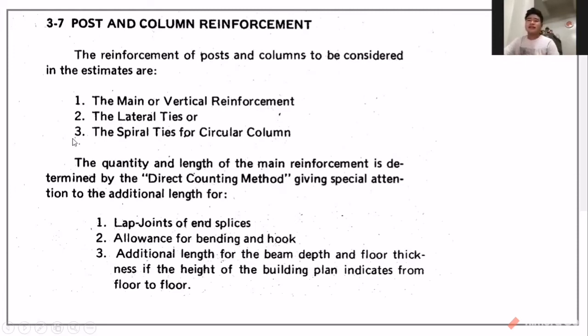So the quantity and length of the main reinforcement is determined by the direct counting method, giving special attention to the additional length for, excuse me, first is the lap joints or end splices.